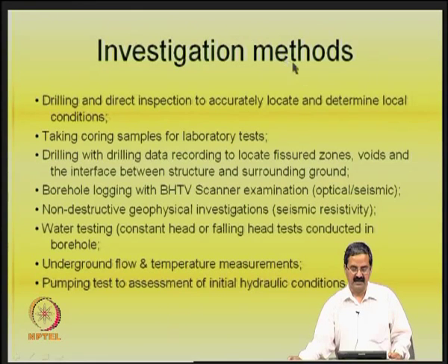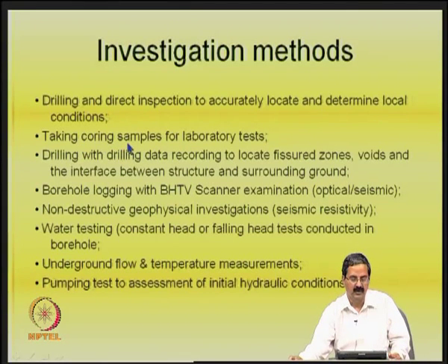In the investigation methods, particularly for grouting, you must be able to have a direct inspection. You must go for drilling to locate and determine local conditions, then take core samples for laboratory tests.